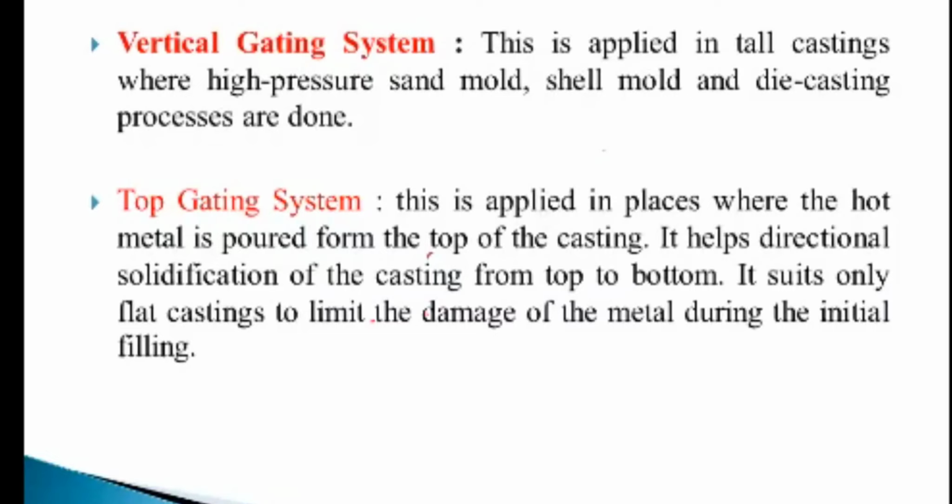Now, top gating system. What is a top gating system? This is applied where the hot metal is poured from the top of the casting. Just now I showed in the figure horizontally in the runner, the metal was moving horizontally and entering inside the casting. But if metal is directly entering the casting from the top, that is the top gating system.